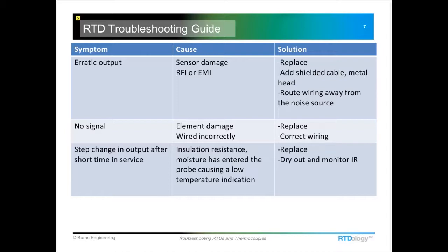If it's radio frequency or electromagnetic stuff from electric motors or communications radios and things, those will generally cause kind of a sawtooth spike in the output. Once in a while, I've heard where people have experienced a step change in temperature, where as soon as the motor comes on or radio gets keyed or whatever, the temperature will either jump up or down.